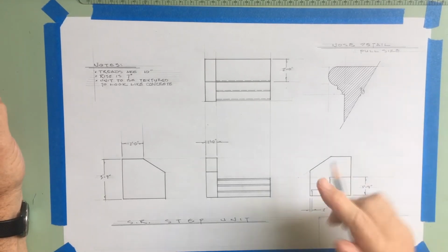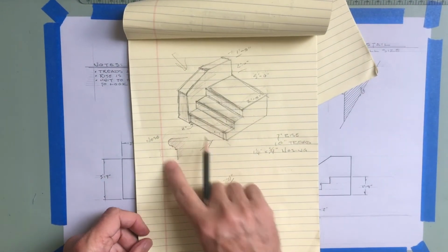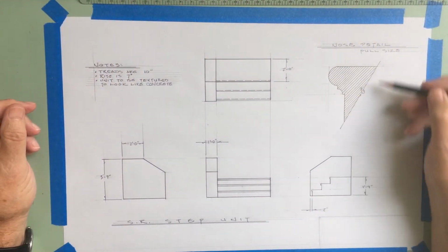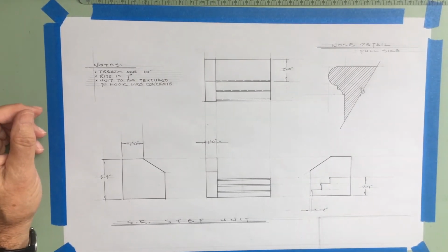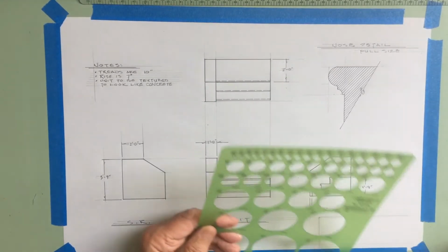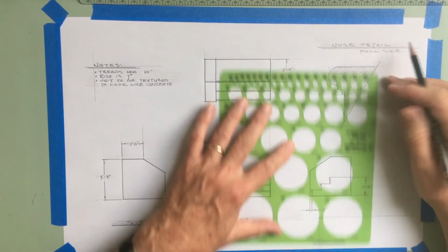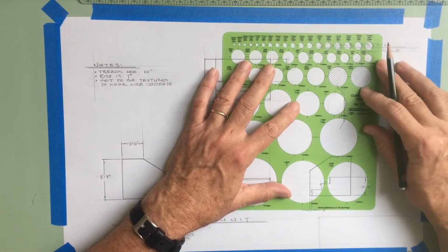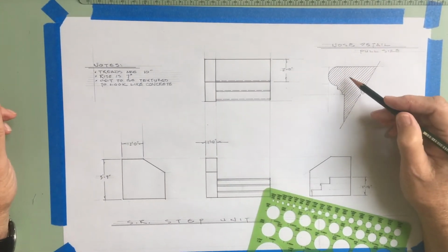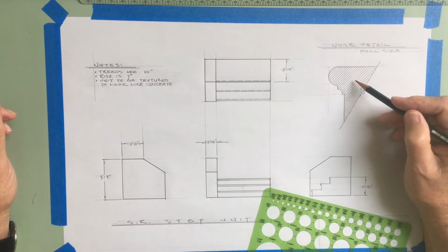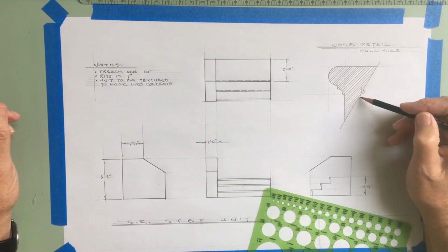I've decided to draw a detail of the nosing because the sketch describes the nosing, and so I drew a detail of the nosing following the sketch and the measurements, and I drew that nosing basically using the circle template. Like this, the top curve of the nosing is a 7/8 of an inch diameter. And then I've also used 45-degree angle thin dark lines that are called section lines to indicate that this is a section view.